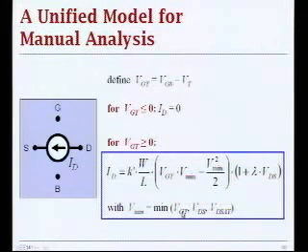That's the minimum between your VGT, VDS, and VDSat. Depending on which of these three voltages you need to calculate, it ends up being your choice when you plug it back in here. If Vmin is equal to, let's say, VGT, you have your good old saturation mode quadratic MOS.